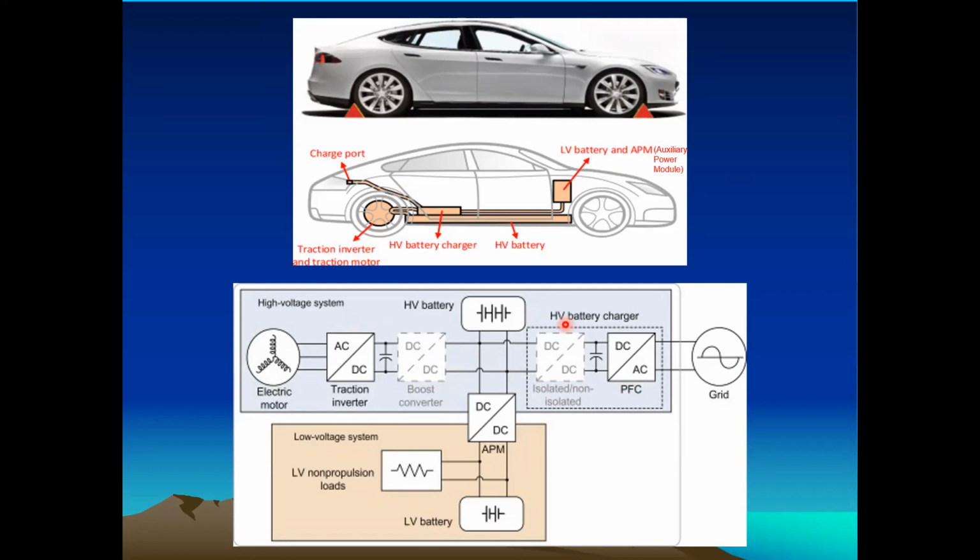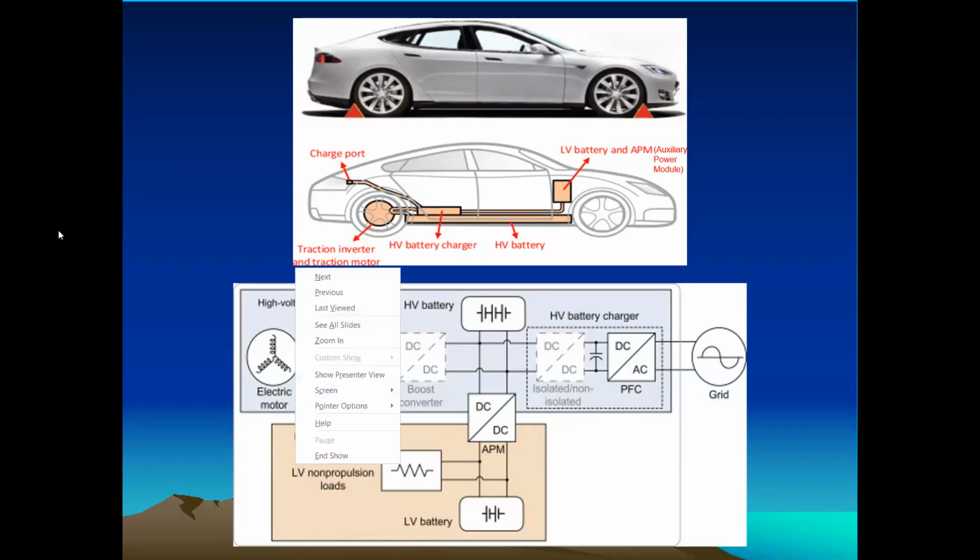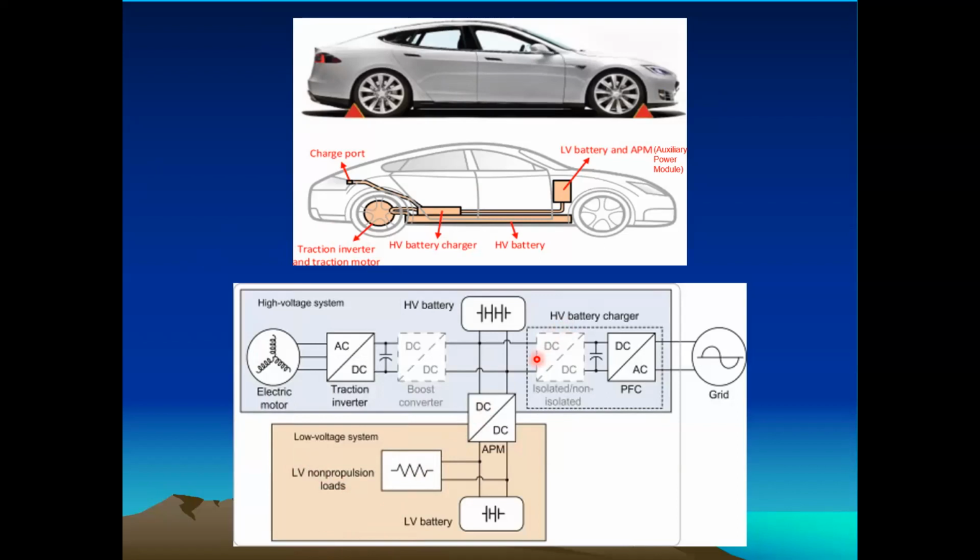power electronic solution. So everywhere, if you see the light you have today, it is an LED light. The LED does not work on AC directly. It needs an AC to DC converter, which converts the available AC to a high voltage DC, and then a DC-DC converter to get your required level of voltage, maybe 1.5 volt or 2 volt. That's the kind of DC voltage your load, the LED light, is looking for. In the same way, the modern fan is made with a BLDC motor. Nobody now uses an induction motor. So the BLDC motor is again working from an inverter, right? So that is driven by a